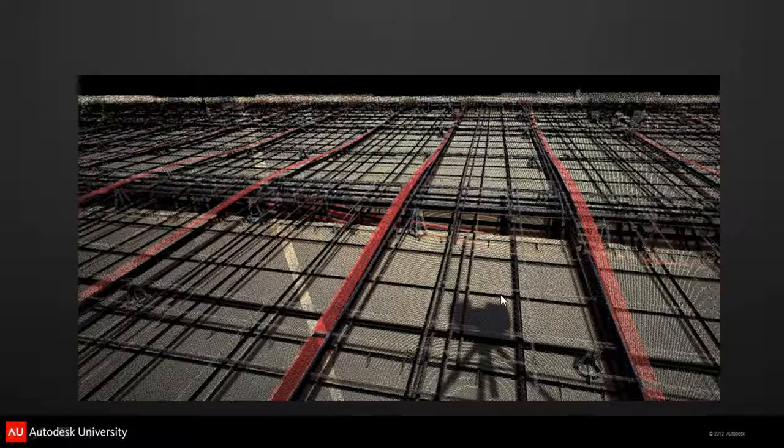So before each pour, we fly out, sometimes the day before, two days before the pour, so that we're there the day before the pour. If it's an early morning pour, we'll go in that same day and laser scan the tendons. And this was for future use, and then we found that some of the trades missed putting their sleeves in at the pour.